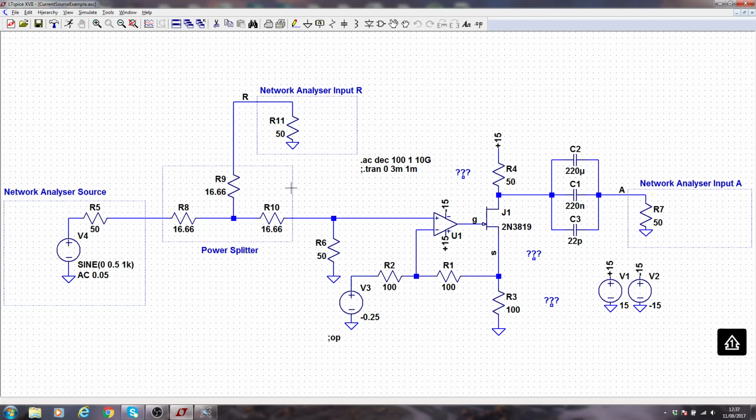So the circuit itself is not particularly important. The purpose of the video is in fact to deal with some layout techniques for high speed, or at least modest speed, circuit boards. The job of the circuit also is not very critical, but we should know at least that the op-amp is switching on the JFET in such a way that a controlled current flows in R3 and in R1. And the controlled current in R3 is designed to be, I can't remember what, let me run it and see. It's 1 or 2 milliamps effectively.